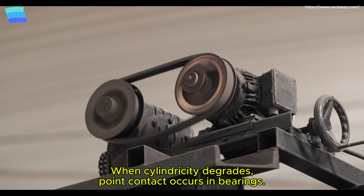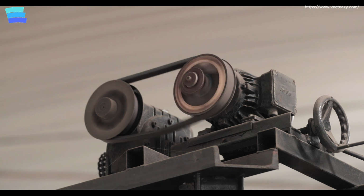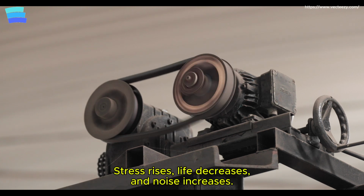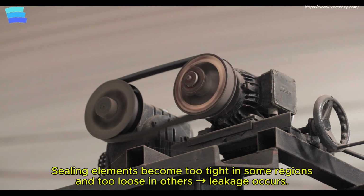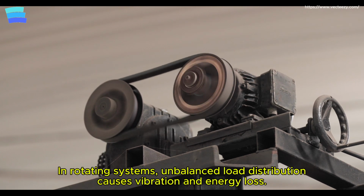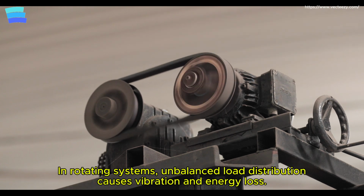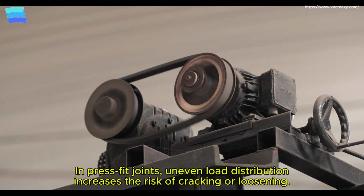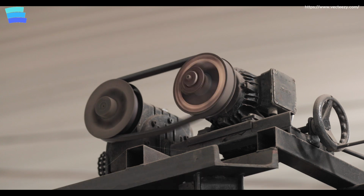When cylindricity degrades, point contact occurs and bearing stress rises, life decreases, noise increases. Sealing elements are overcompressed in some regions and loose in others. Leakage occurs. In rotating systems, unbalanced load distribution creates vibration and energy loss. In press-fit joints, the load does not distribute evenly. The risk of cracking or loosening increases.